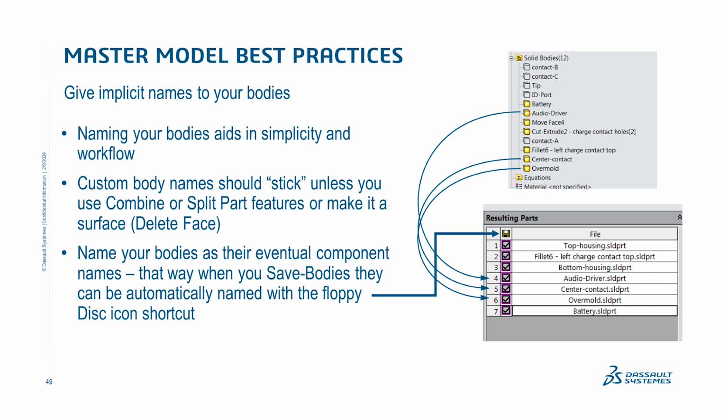So it usually makes sense to really name these towards the end of your design process so that once everything is established and you do a save bodies or insert part, it's very clear what these bodies are representing as far as a component.